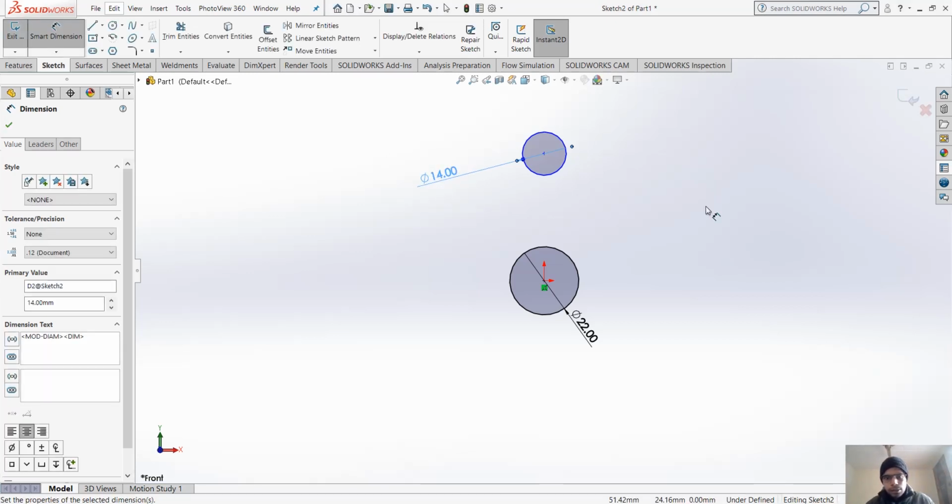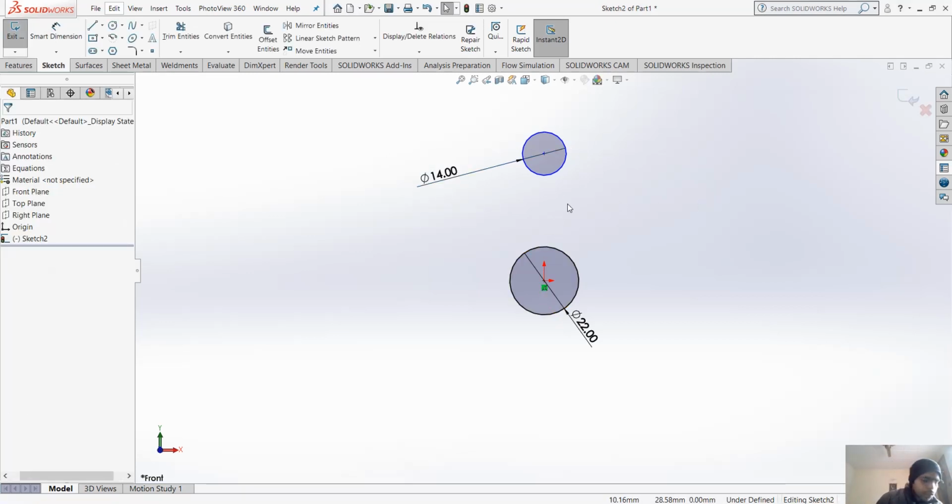And actually in SolidWorks you are seeing this blue because it is not defined, and everything is defined from the center. Since I have not given the distance from the center, it is showing me that it is not fully defined. So the distance from the center is, this is 22, this is 78, and this is 58.